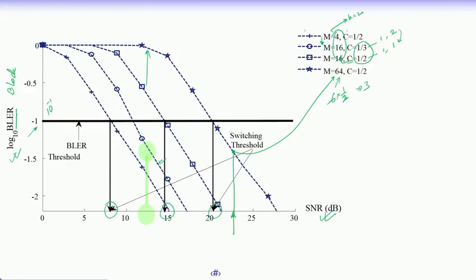So, which means 3 information bits per second per hertz one can use over here. Whereas, if the SNR condition is below the minimum threshold, so this is let us say gamma 0, then one does not find any modulation code rate to have a BER which is lower than this threshold, and hence one does not find it a good condition to transmit the signal.